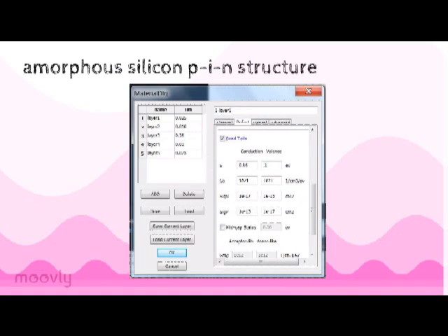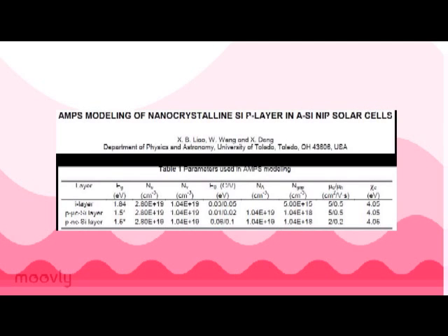Many people have used AMPS software to model amorphous silicon in a similar way. In these works, they use input parameters based on experimental results from time-of-flight measurements. For example, one group who was studying hydrogenated amorphous silicon used AMPS to show that hole drift mobility measurements and measurements of temperature dependence of the open circuit voltage could be used to estimate parameters.